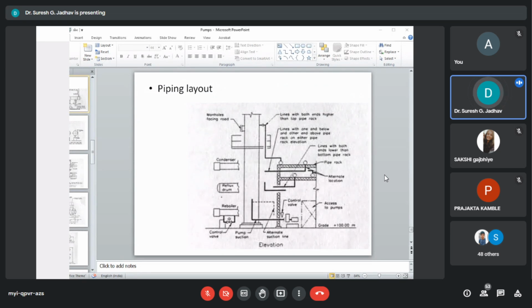The steam lines to the reboiler are taken from the top of the main header to avoid excessive condensate drainage to process equipment. These lines can run at the same elevation as those lines approaching the rack from the tower. On a distillation column, the largest lines are the overhead vapor lines and the reboiler downcomer and return. These lines should have the simplest and most direct configuration to minimize pressure loss and cost.